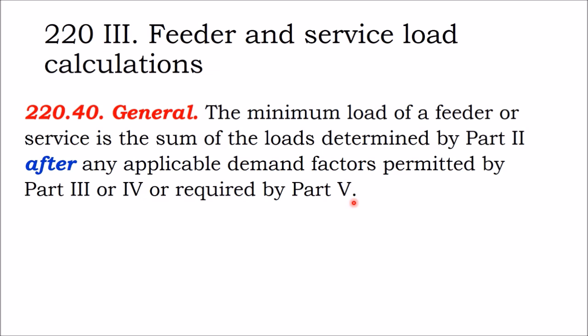The minimum load of a feeder or service is the sum of the loads determined by Part 2 after any applicable demand factor is permitted by Part 3 or Part 4 or required by Part 5. What that says is there is a minimum load that you can design for a dwelling unit.